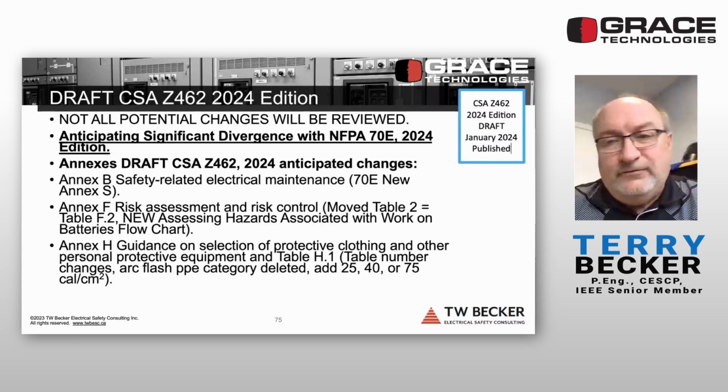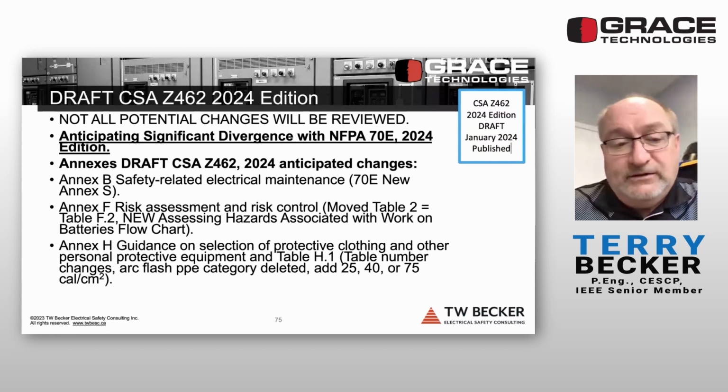So any table or any information, any language related to arc flash PPE category is wiped out in Z462. In turn, we had to update Table H1, which was the arc rated clothing level table, if you use the arc flash PPE selection table method now.